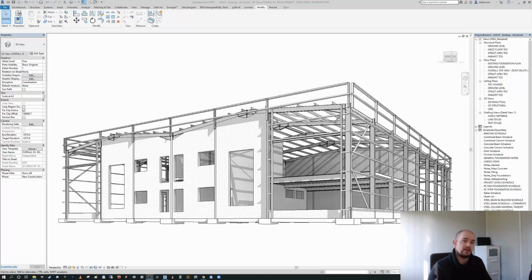So number 15 is just to let you know that you can actually give greater control to your selection tool within Revit, okay? So you'll notice in the modify tab here, on the ribbon, there's a little drop down on the selection. And this actually gives you a greater control of how you can select elements, okay? So here, what I have is the default selection tool set and how it's set up.